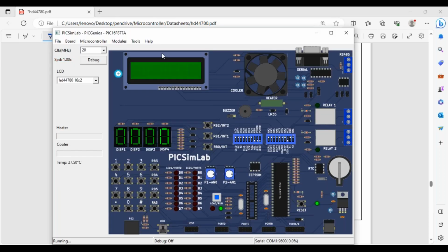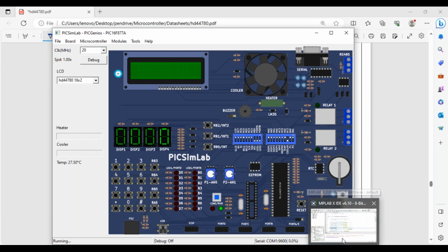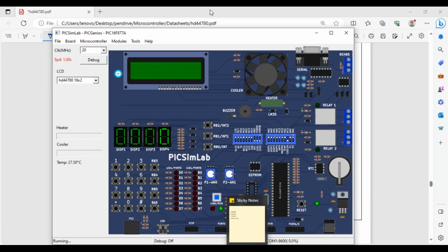Now if you observe the CLCD which is available on this board, can you see there are two lines here for the sake of displaying the data? Yes. So I can choose whether to have the data displayed in two lines or on a single line. That is up to me. I have to say whether I am going to choose two lines or one line with the help of the N and F bits.